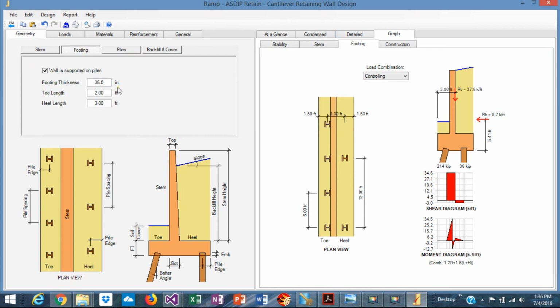We can increase the thickness a little bit more if we want, but in this case, if we use the strut and tie theory, it's obvious that this vertical resultant load will be distributed to the piles, similar to a truss. So probably the shear capacity is going to be okay in this situation. This is the moment diagram, so we can size the rebars accordingly.